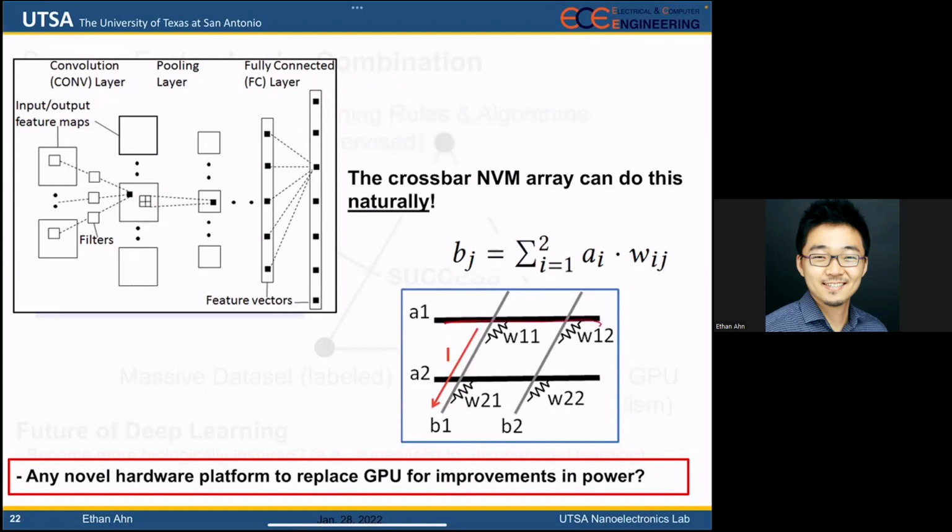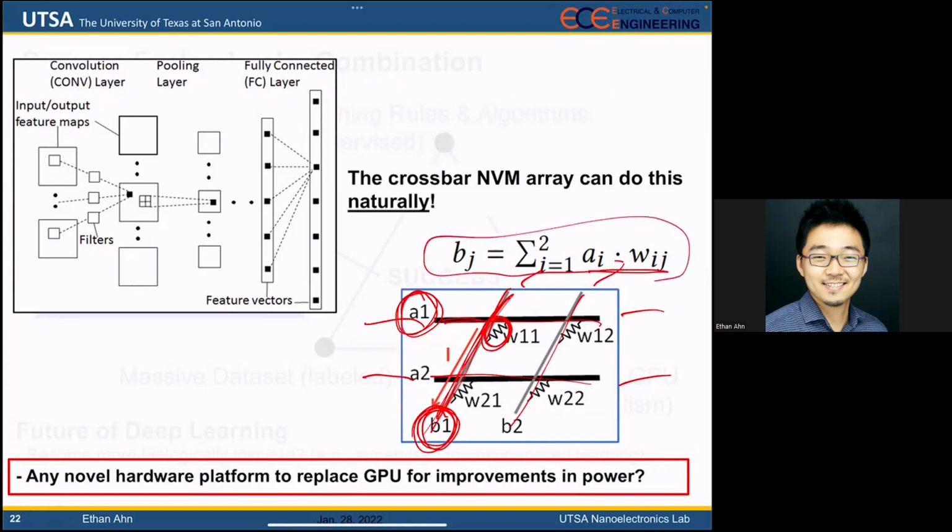So you have these crossbar arrays in memory, and sometimes you call them bit lines and word lines and all that. Because we know the current in one specific line is the summation of, for example, the voltage in each line times the conductance in between, it will be given by this equation here, and this is exactly the matrix form of calculation. Because of this similarity, non-volatile memory can also be used very well to do this neuromorphic computation.